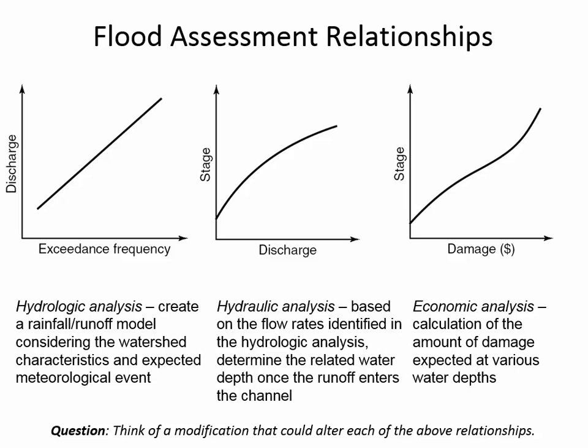And so you can try and restrict urbanization. And they're doing a little bit of that in Huntington nowadays. They're starting to charge a stormwater fee. The new athletic practice facility by the football field, they had to put in a big underground rainwater storage vault to try and hold on to the first inch of runoff. And I think they also have to pay a stormwater fee. It's a little bit unclear to me, but they're trying to discourage people from just paving everything, because when there's lots of parking lots and roads, that increases the curve number and it makes that curve higher.